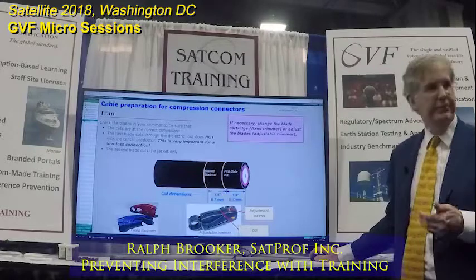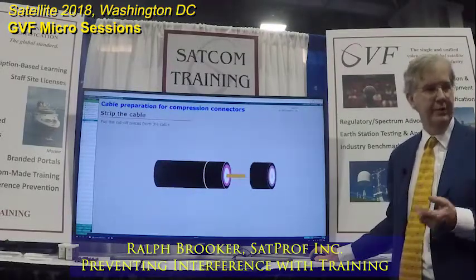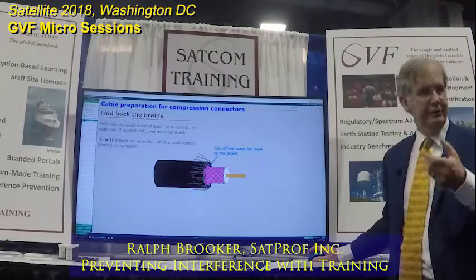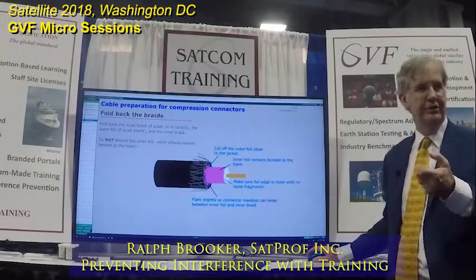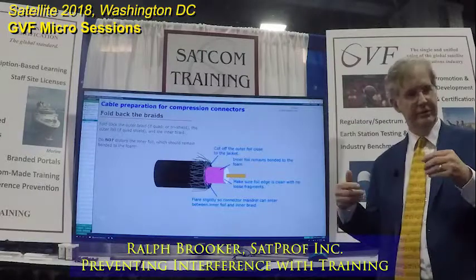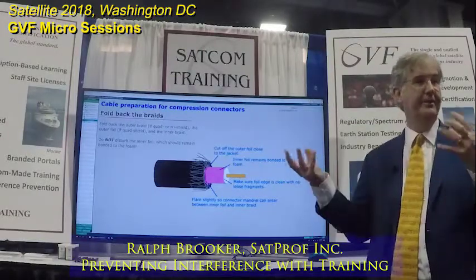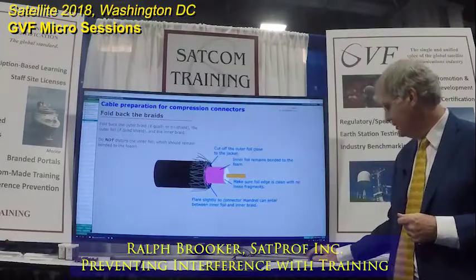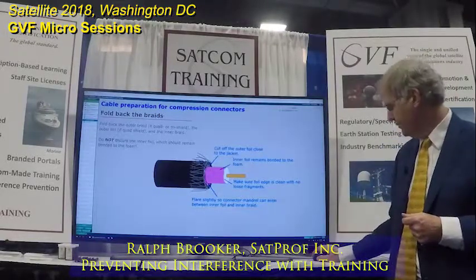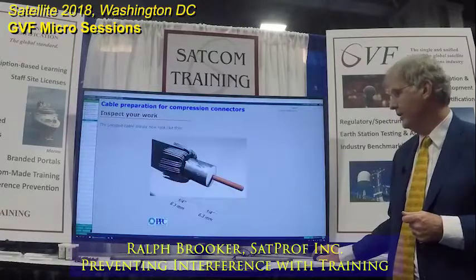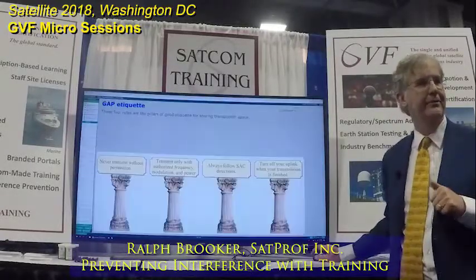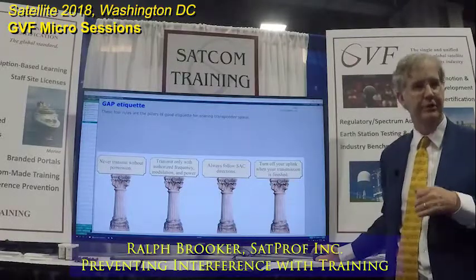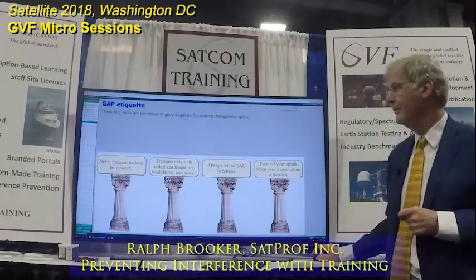So it's really important when you're training technicians that they know the right way to correctly terminate cables, because most of those issues are that the grounding is not properly connected to the shielding, and the connector, if it just is connected through the center, acts as an antenna, and it's a very efficient monopole antenna. So we have lots of animations for that, and we teach them the principles of it, and later on we have a decision-making simulator that makes them walk through the correct processes for preparing, say, quad shield RG6 cable.